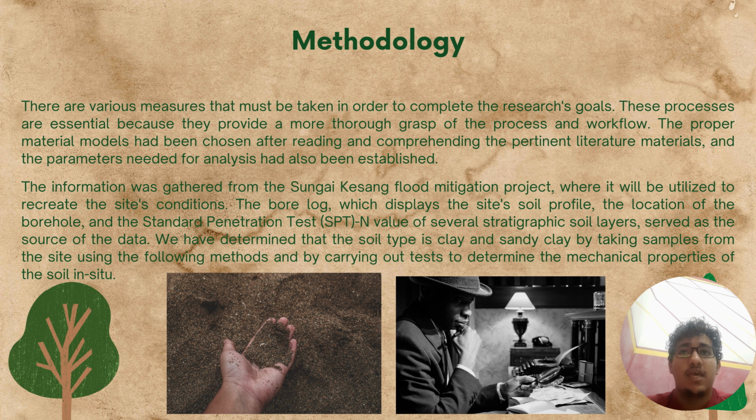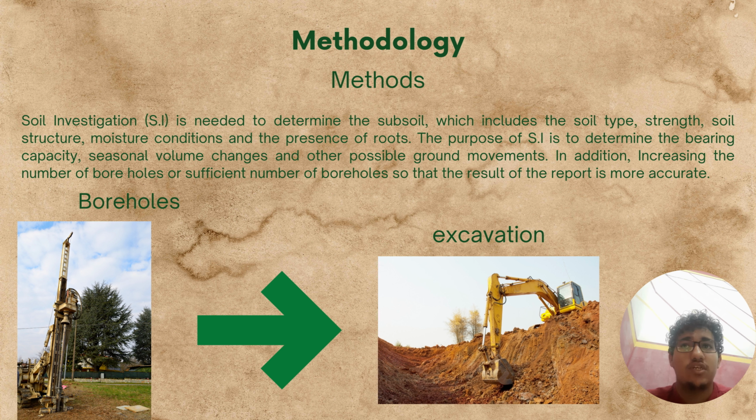Investigation is needed to determine the subsoil, which includes the soil type, strength, soil structure, moisture conditions, and presence of roots. The purpose of the soil investigation is to determine the bearing capacity, seasonal volume changes, and other possible ground movements. In addition, a sufficient number of boreholes makes the result of the report more accurate in determining the problems that may occur during excavation, which can cause the soil to deform.